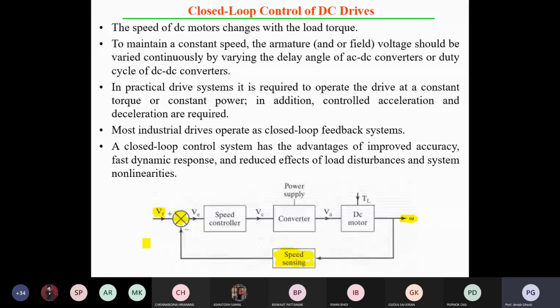So why are we using the PI controller? What is the motivation for selecting that controller? Normally the basic motivation is that in a PI controller you can minimize the steady state error, that is, the error when you compare the actual value with your reference. So the actual voltage, the actual speed, is compared with your reference speed, in terms of voltage. Okay, the unit of the reference speed is voltage. You compare them and you get the error value, and that error value should be minimal.